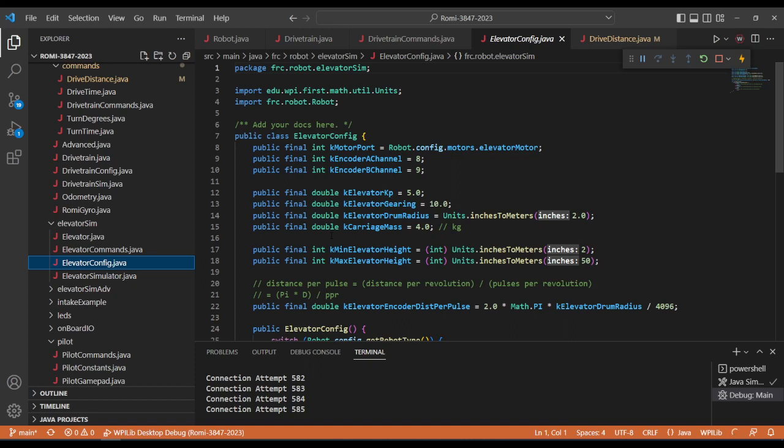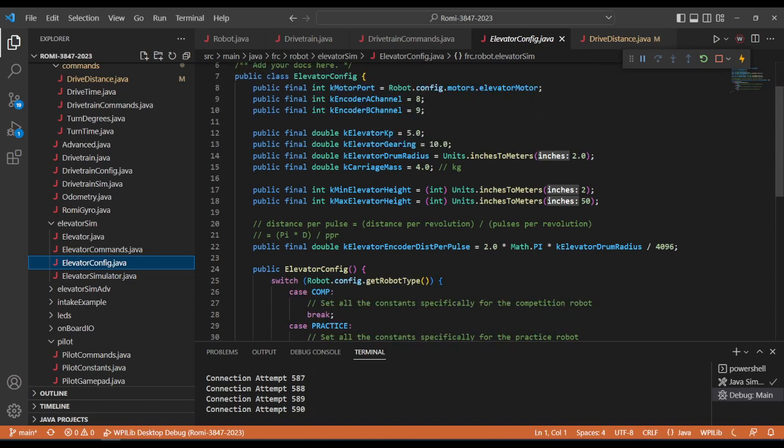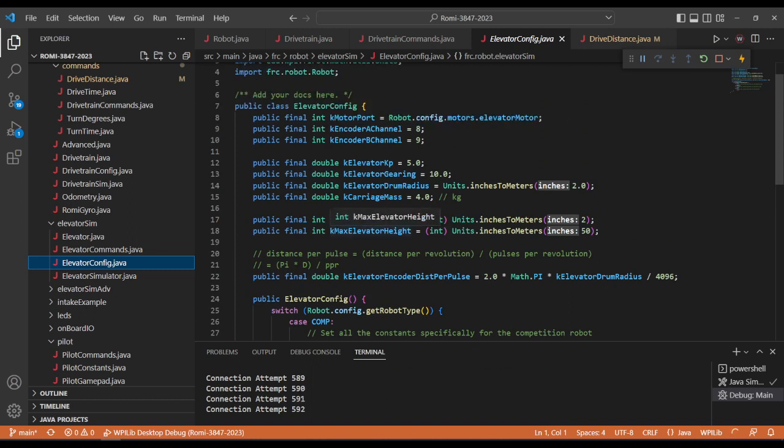The same way that we tell the launcher motor to go to a speed, we have to tune a lot of little settings so that it knows how it's going to get there, and how it even knows that it's finished. All of those things have to happen. So that's a lot of what this ends up being, tuning a lot of settings in the config files to let it know how to do some of those things.